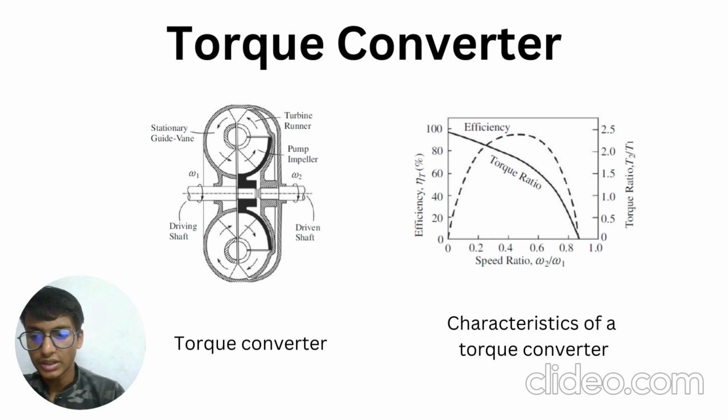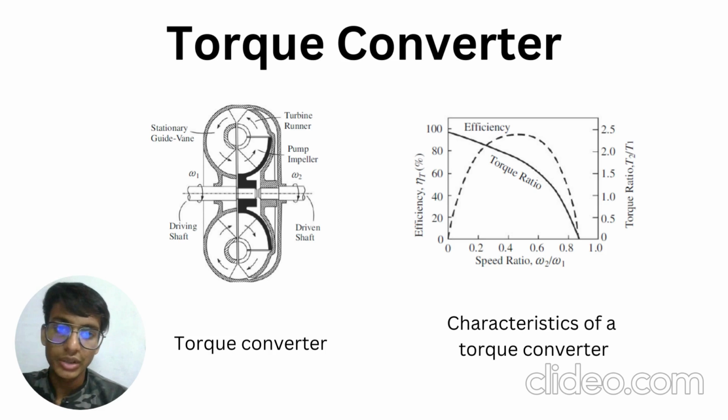In a fluid coupling, under conditions of high slippage, the fluid flow returning from the turbine to the pump opposes the direction of pump rotation. This leads to a significant loss of energy. Under the same condition in a torque converter, the returning fluid will be redirected by the stator so that it aids the rotation of the pump instead of impeding it. This leads to recovery of much of the energy in the returning fluid, in addition to the energy being supplied to the pump itself.